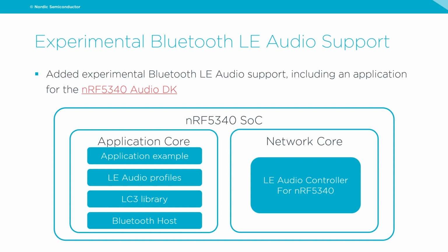So the support that we have in the SDK now is that we have the LE Audio controller for the nRF5340. It's intended to be flashed on the network core of the nRF5340 SoC.